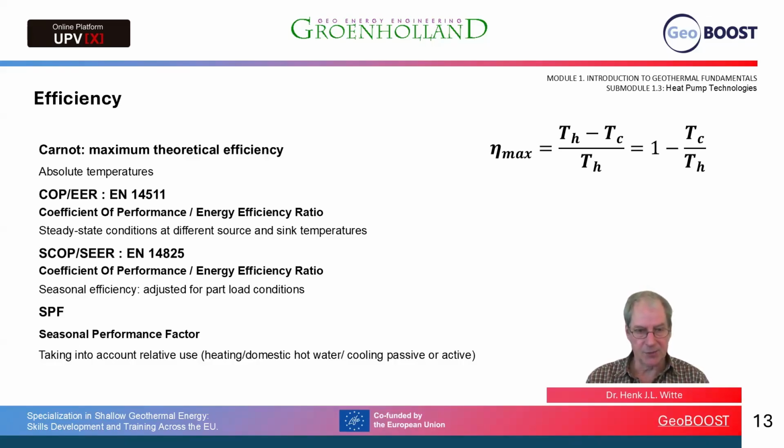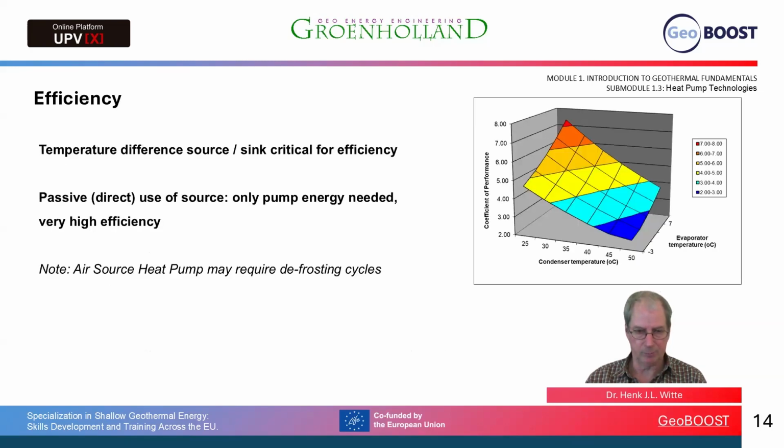This still does not give us the real efficiency, the SPF, the seasonal performance factor, because it does not consider the relative amounts of energy between heating operation, domestic hot water production, and active or passive cooling operation. So the seasonal performance factor actually does this and can either be calculated or measured in the building and provide us with a real efficiency of the system.